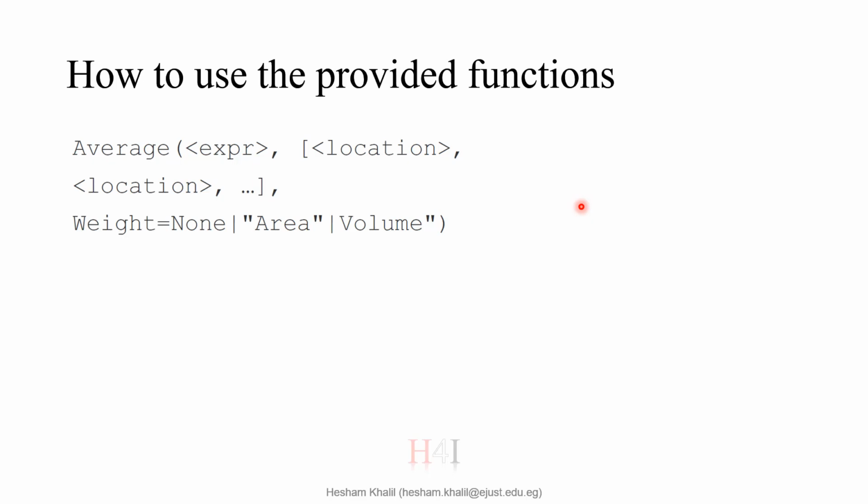Like in the same case which I just explained, if you want the absorptivity of the water, hypothetically speaking, it changes with temperature, assuming that. So you need to know the average temperature, so that you calculate the average temperature, then calculate the absorptivity, then multiply it by the radiation to calculate how much energy is absorbed. So you need to define the average. How to define the average? This is the average function, and how its description is written.